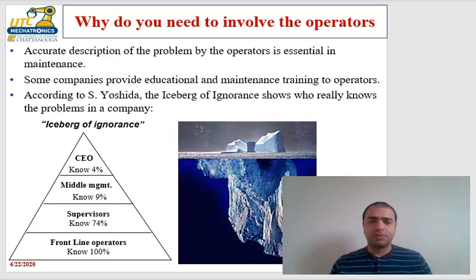An overload trips. An overload basically is an element that detects current overloads. If the motor draws large current, it trips and stops it. So a very common problem is when the overload trips, not because the motor is overloaded, but because the bearing is not lubricated. When bearings need lubrication, the friction will cause overload and the motor will stop. So this problem is difficult to find.